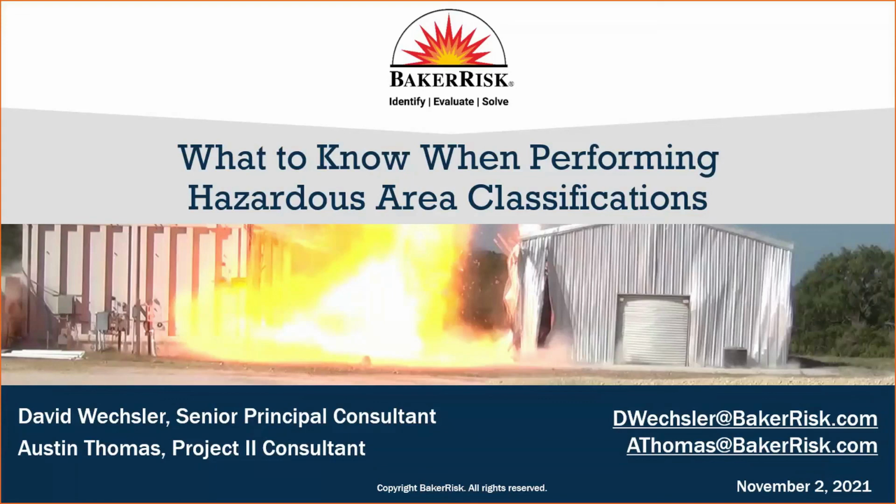Excellent. Next question. When Baker Risk prepares a facility siting study, they typically use leak sizes of 1/2 inch, 2 inch, and 6 inch, so the flammable endpoint can be a very, very long distance. For scenario-based HAC, the leak size is typically very small. Can you comment on a potential discrepancy between facility siting studies and HAC?